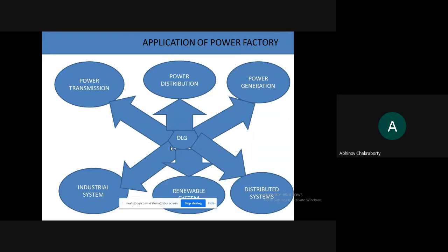So here is the renewable system study that is a part of your DIgSILENT software itself. The distributed systems, that is basically the grid connections. I am producing solar energy at my local unit. I want to connect it to the grid. The grid has the AC mains. So how can I connect it? And if I am making the connection, whether the connection is viable, whether my total arrangement is okay, is perfect, in order to check it out, you again have to have this simulation done on your DIgSILENT PowerFactory.